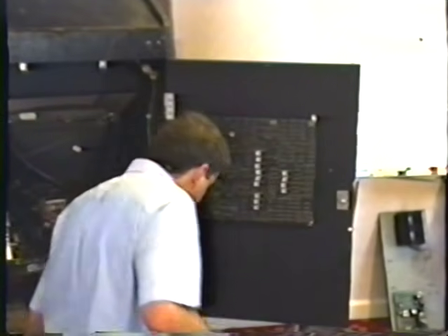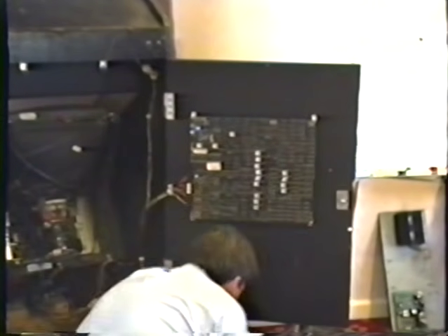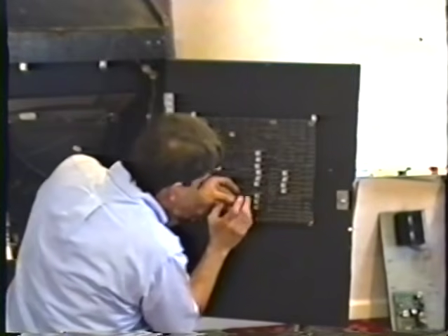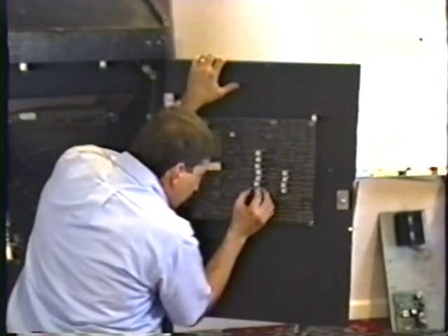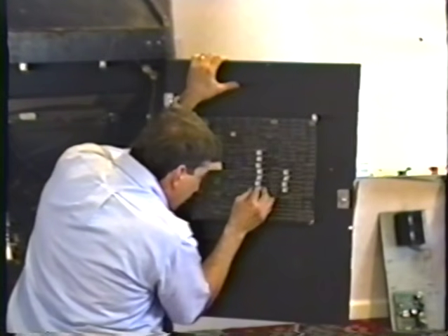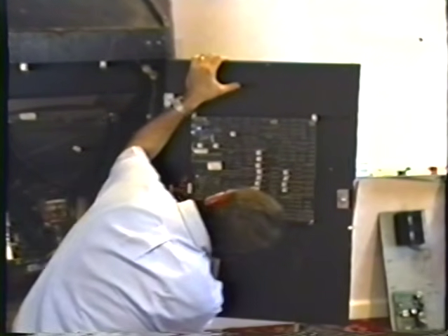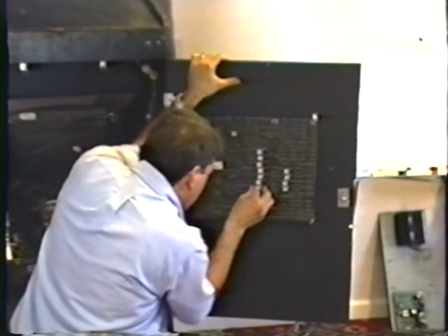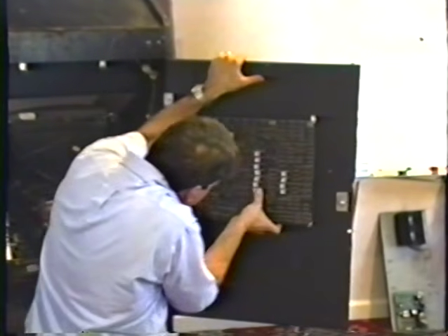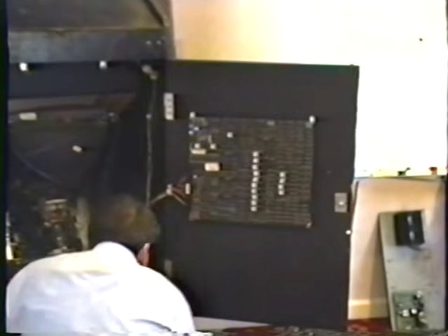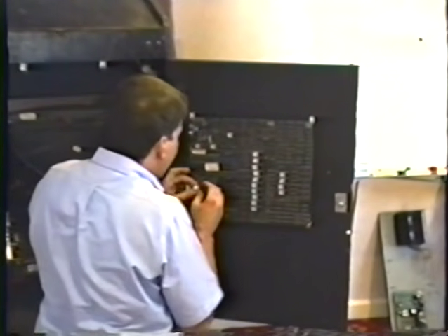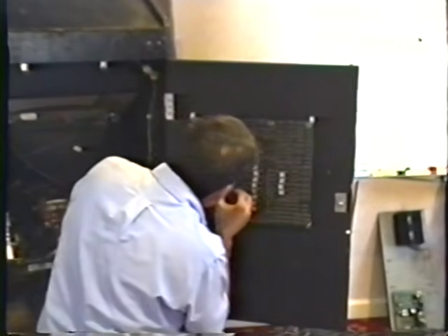Let me just put this chip back in here. Make sure the notch is going the right direction. What I usually do is put in one side part way, then put in the other side. Are they all lined up? I hope so. That's not my game anyway, so it's not that big a deal. There we go. And let me just put back the integrated circuit that I pulled out that actually caused the failure.